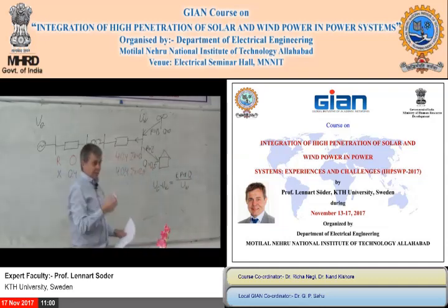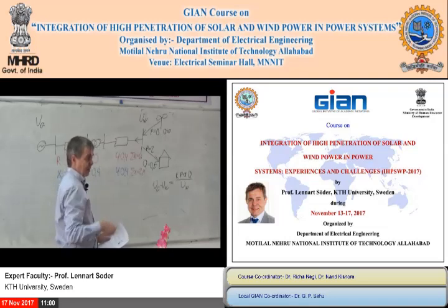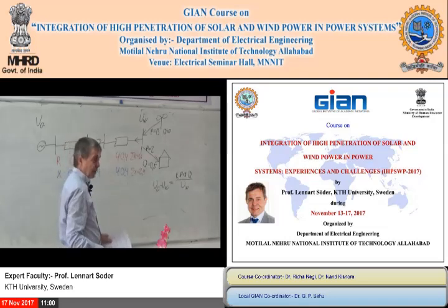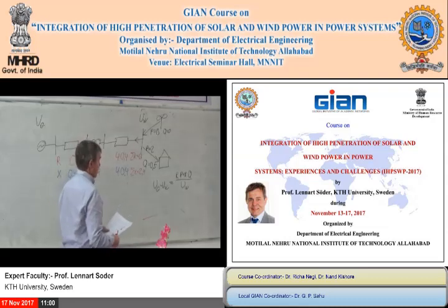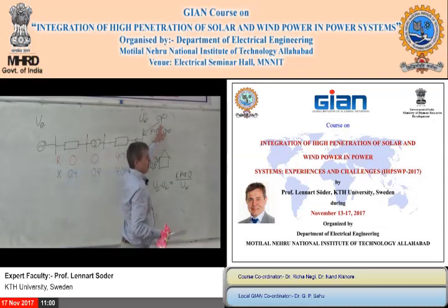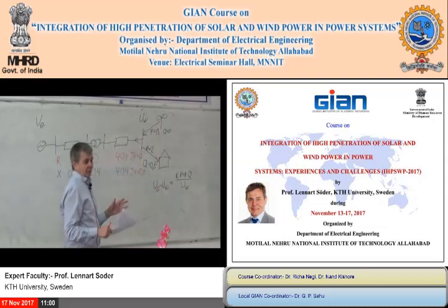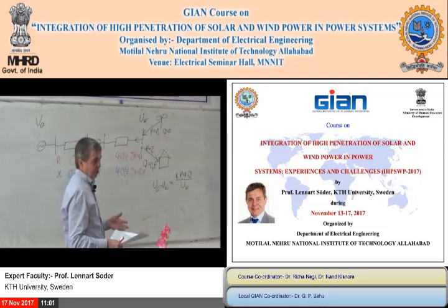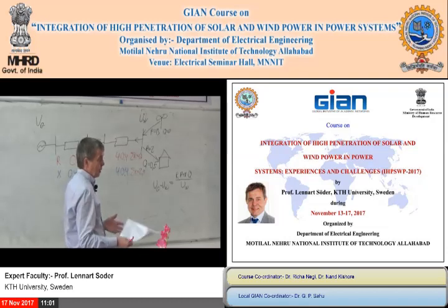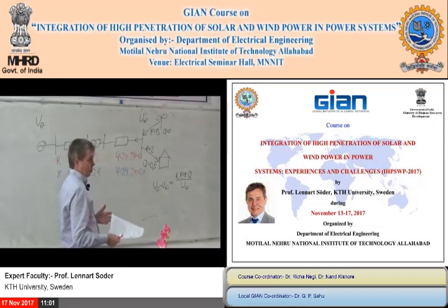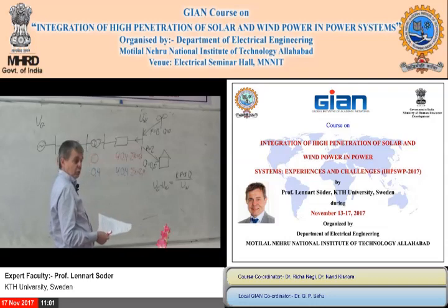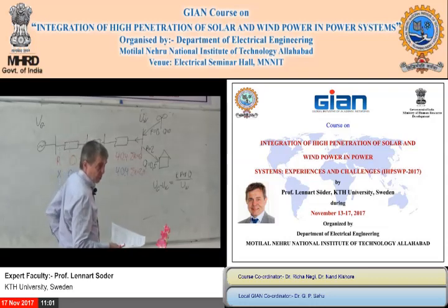Then it's also like this, that to change P means in reality that you are changing something that you can get money from, because P is producing power, while reactive power is something that you probably have here. So on the other hand, this is not exactly trivial. What is the most important thing? Because the question is more economic, from the economic point of view, it's of course always better to do something in the Q than to decrease the wind power production.